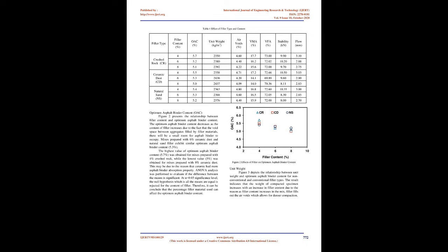Mineral filler. To investigate physical properties of fillers and their suitability in road construction, various tests were conducted, and the results are presented in Table 2. Asphalt binder. A series of asphalt tests, including penetration, softening point, flash point, solubility in trichloroethylene, ductility, loss on heating and specific gravity were conducted. Table 3 depicts the physical properties of 80/100 penetration grade asphalt binder.